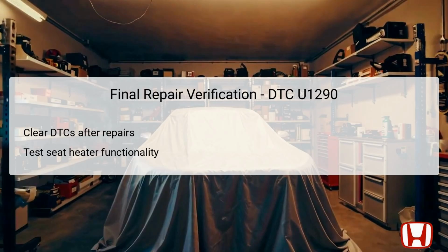After conducting the necessary repairs on the front seat heater control unit and addressing any issues with its power or ground circuits, a final verification process is essential. Begin by clearing any diagnostic trouble codes stored in the vehicle's system. This ensures that you can obtain a clear reading on whether the issue recurs after repairs are completed.